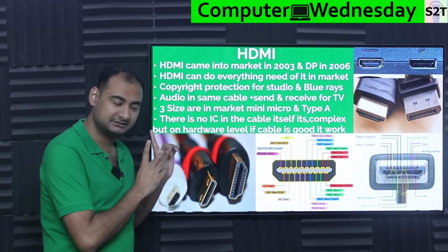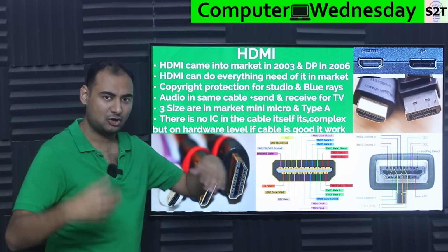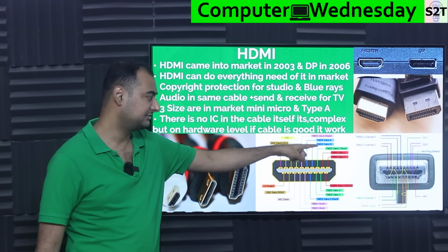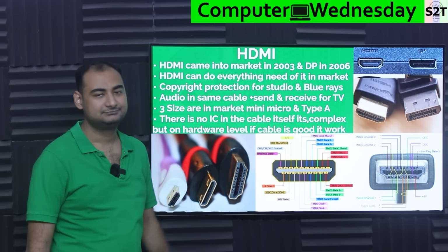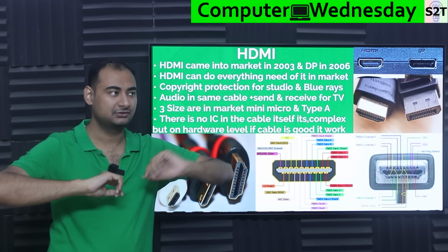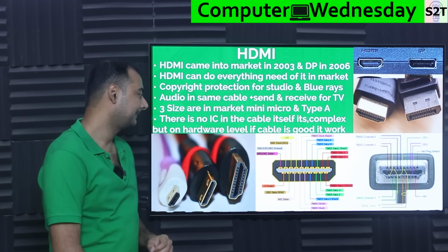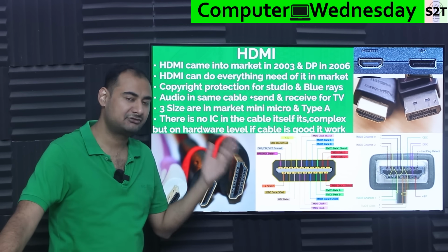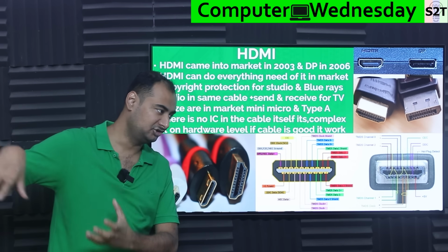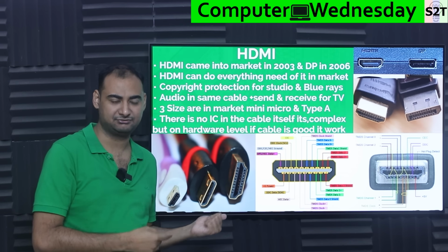This is one thing that they designed from day one. So it has almost the raw data, as in the red channel, that's the red color that you see, green channel, and the blue channel, and it goes to the IC on the device, and it decodes it into red, blue, green, and a timing signal. Because it was designed from day one as a video output, it has a really good unfiltered signal, and that's why it requires stupid numbers like 40 Gbps.